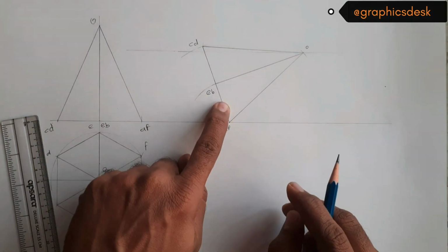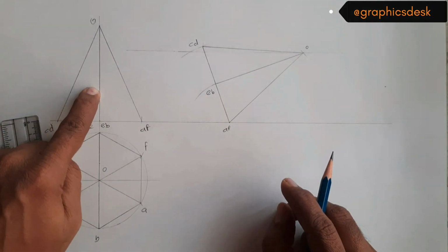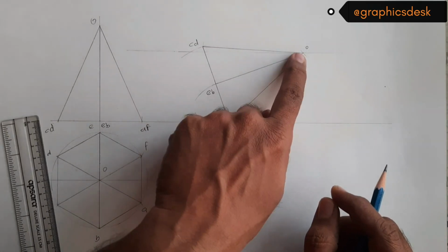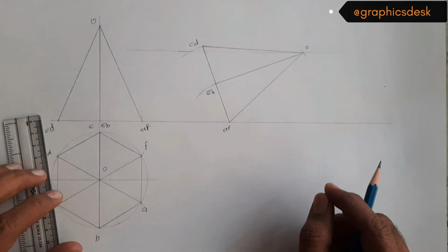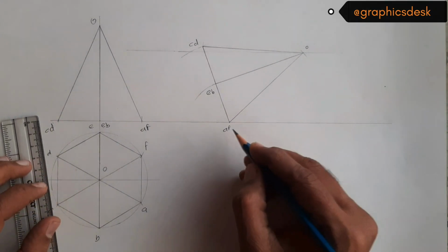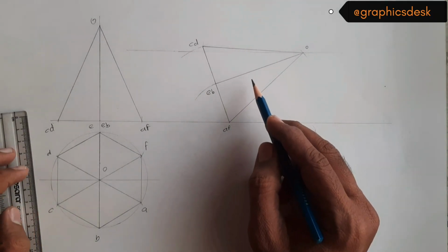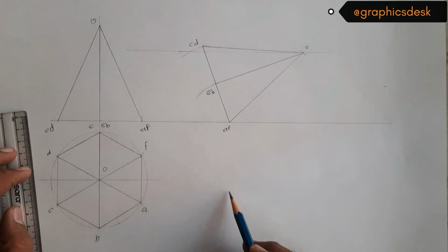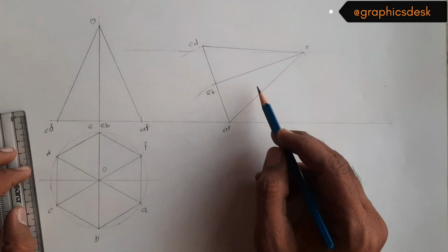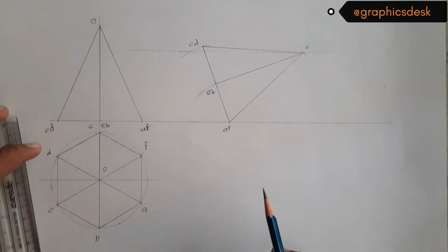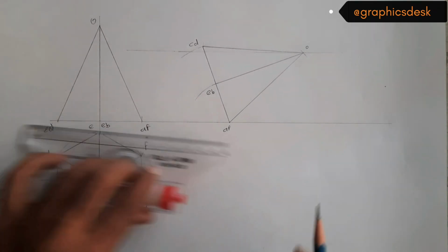Now this is our top view, which is same as this, but meeting the condition of apex being 60 mm from the XY, that is horizontal plane, and resting on the edge. So that's our top view after tiltation. Now let's draw the top view. This is the front view after tiltation. So we'll have to carry the projections.